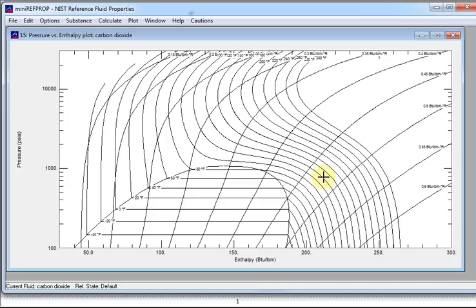And depending on how far I want to go, because this is a line of constant pressure, true? Horizontal. What are these other lines? These lines are constant temperatures. So 0 degree F comes across, then scoots down. What is this line way out here? That's a 300 degree F isotherm. That's 300 degrees F. This one's 280. This one's 260. So we're going to have to increase the pressure to get the temperature of our CO2 high enough to reject heat in the condenser.